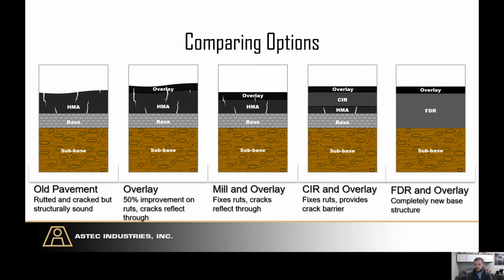You can see it's a little thicker because of that slightly higher air void content, but we end up with the overall same strength as far as structural coefficients. And it just doesn't have that structure to let the cracks reflect through. So that will increase the pavement life and service life of that pavement even farther and extend the curve even